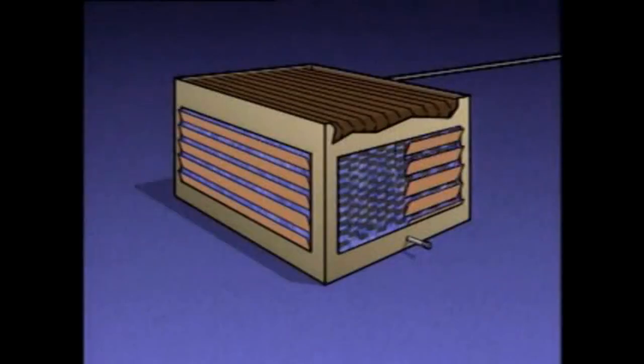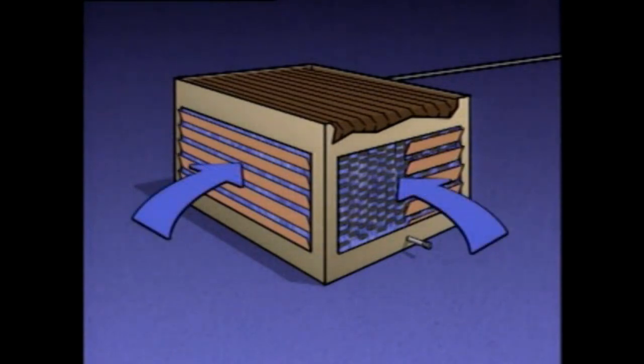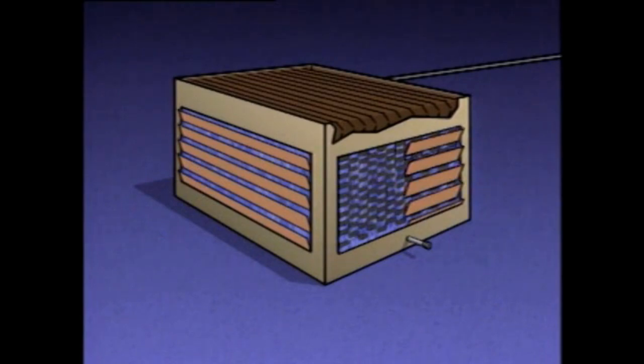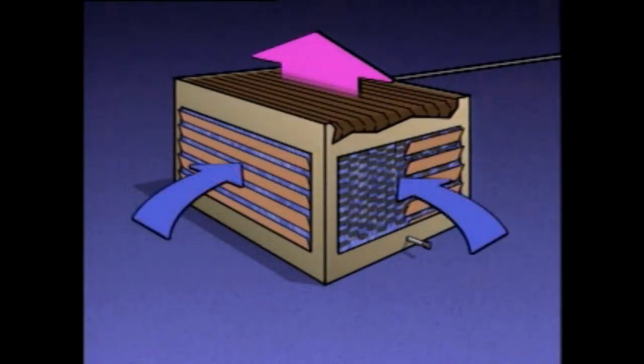into two broad categories: natural draft towers and mechanical draft towers. The term draft refers to the flow of air through the tower. In a natural draft cooling tower, air flows through the unit naturally without the aid of mechanical devices. As the water evaporates and heats the air, the air inside the tower becomes warmer and less dense than the air surrounding the tower. As the less dense warm air rises up through the tower, denser, cooler outside air is drawn into the bottom of the tower.